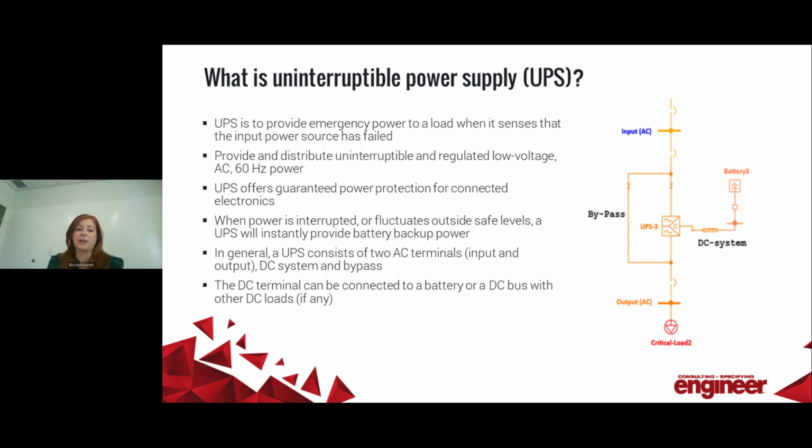Therefore, it meets the definition of a reliable AC supply as defined by NEC. The availability of its output approaches that of a DC supply. The UPS consists of several pieces of equipment centered around an inverter.